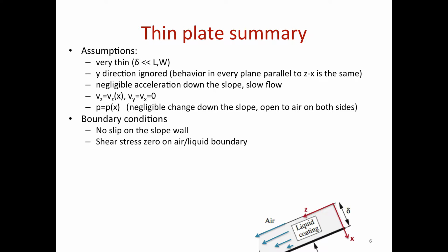And one important thing somebody already noted is that we have to always know boundary conditions. And quite frankly, if anything is going to give you pain, those are boundary conditions. So if you even have a partial differential equation, it's valid at a point that is sort of an internal point of your geometry. When you're close to the boundary, your partial differential equation or computing derivatives are valid only up until that boundary, but not across the boundary. So this is where you have to place your boundary conditions, and you have to know the values, and that shapes your solution in a great way.